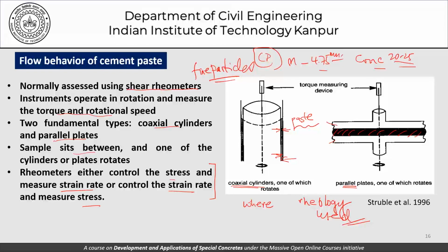As far as we are concerned, we could use these experiments directly only when we are trying to work with, let's say, grouts, and trying to study how grouts can be injected into cracks. Those cracks at times are extremely thin or extremely narrow passages through which we want to push a grout without segregation. So there, yes, we can probably use some of these thought processes, some of these experiments to determine the properties of grout that we need.